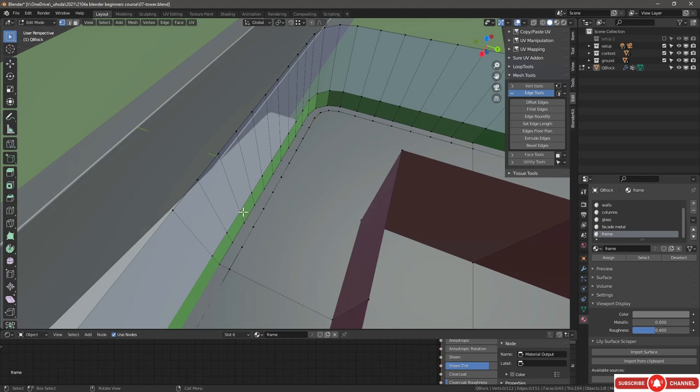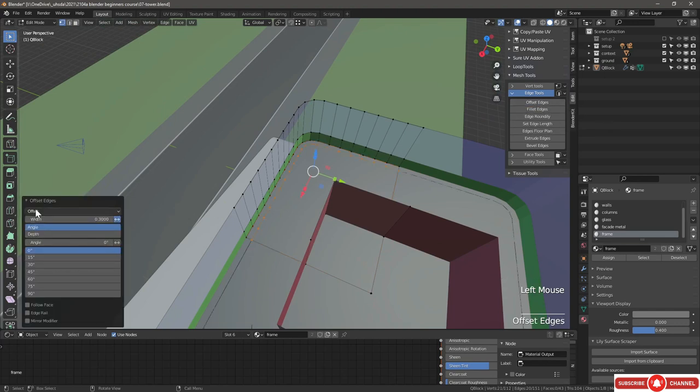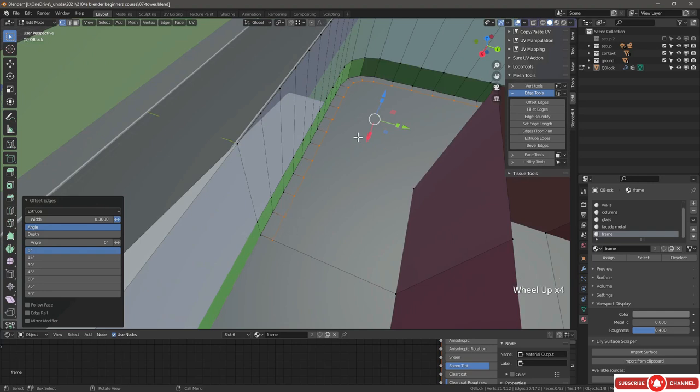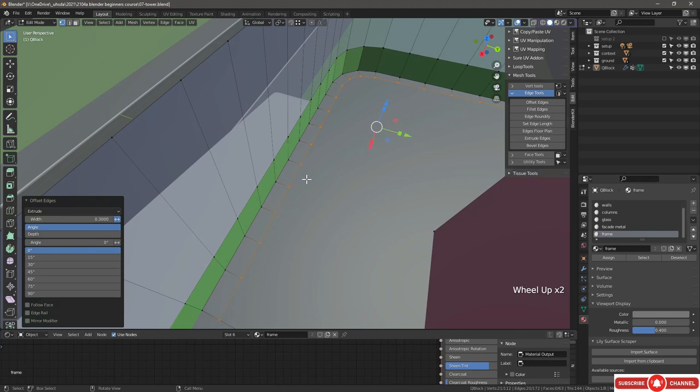Okay, so there's a slight error that I need to fix, and that is that the cube locker add-on only works with faces, and these are not faces. So we'll just need to temporarily create faces again. So I'm going to go into edge selection, Alt click, X, vertices, select this edge here, go into vertex selection, shift deselect this vertex, offset edges again, and this time we want to change from offset to extrude. So we're making these sort of fake faces for the time being that we're going to erase later, but we want to use them as snapping helpers.